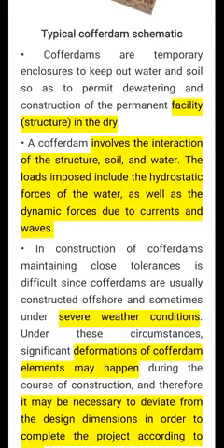Now, a cofferdam basically facilitates construction in a dry condition inside the soil. A cofferdam involves the interaction of the structure, soil as well as water. The imposed load includes the hydrostatic pressure, because these are inside the water. That's why the hydrostatic pressure will be exerted on it.